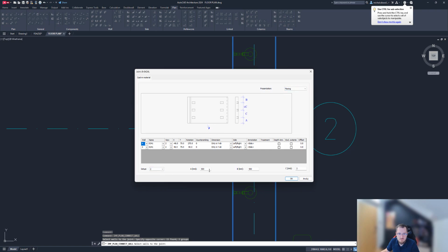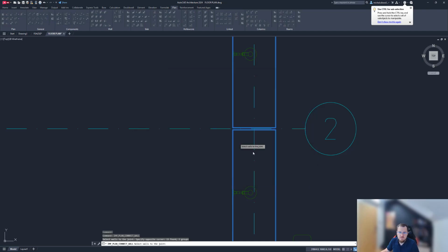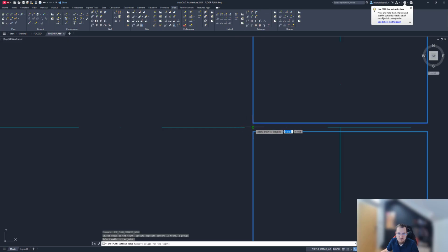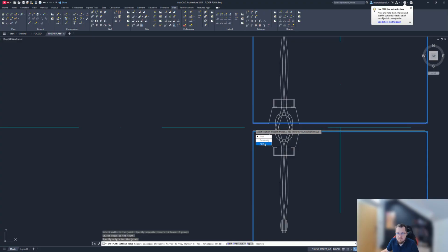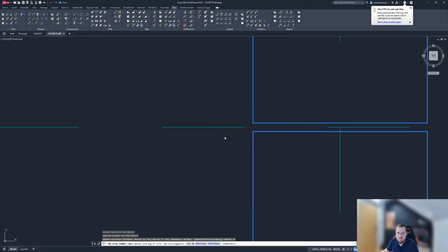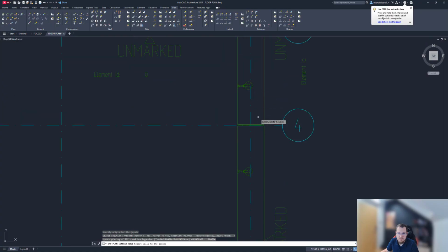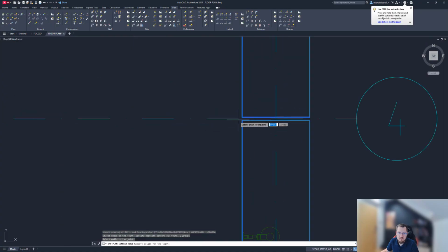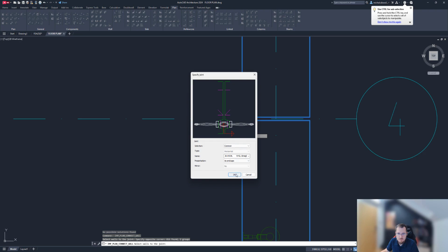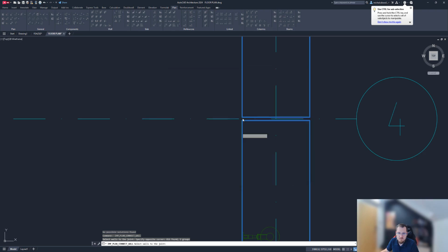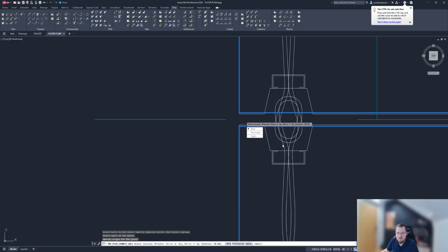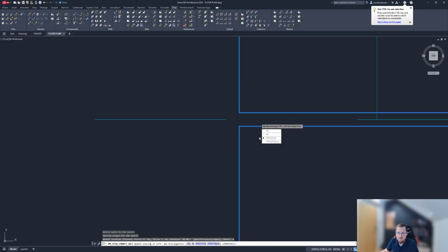Let me go ahead and actually do that this way. Cast-in material, just to make it different, I'm going to leave it at 2, so you know that those sides are different. And the origin of the joint, let's make it in the middle, and apply and update all, like that. Walls are now connected. I can do the same thing here. The origin of a joint, that's because we need to be somewhere in the midspan of that. Apply, update all.